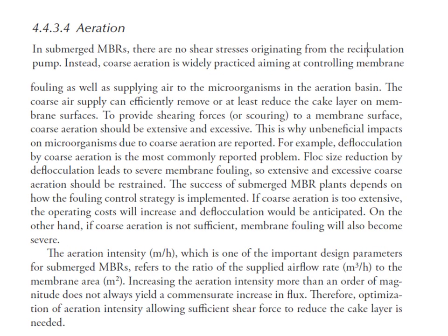So the shear stress by the pump or other mechanical method is not very good for operating this MBR system. So that's why the side stream MBR is not favored by the industry. On the other hand, in submerged MBR, there's no shear stress by the pump.